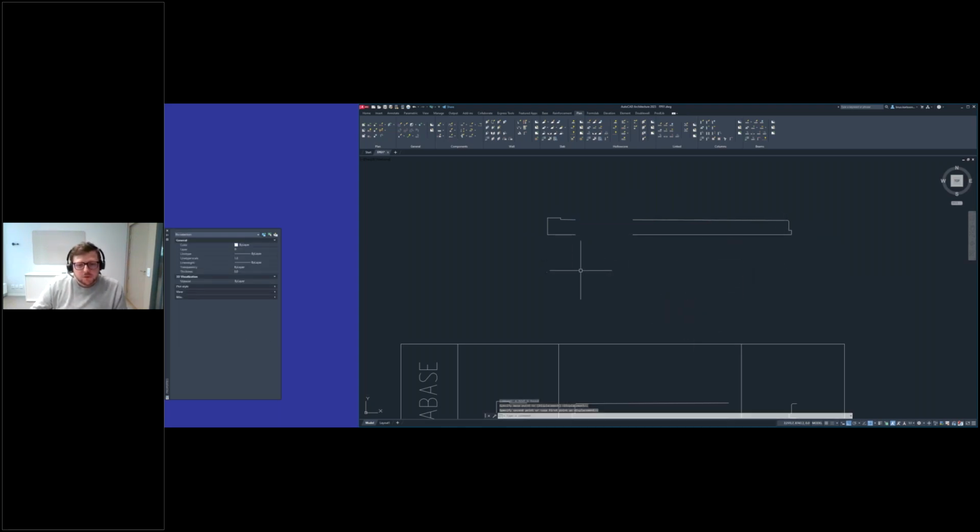The first issue that we see is that this one is mirrored, because the rule of thumb when it comes to end caps is that we start on the lower left corner, and now we have the lower right corner because it's continuing in this opening here.